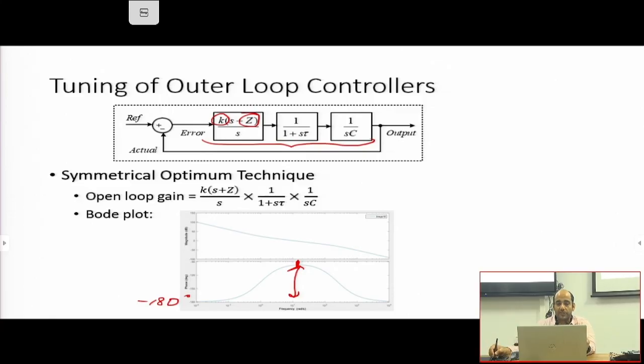So you know what happens now if you see the transfer function here. I hope you can agree with me. If you just change the gain K, it will not affect the phase plot. It was just a gain without any angle. Gain K doesn't carry any angle, right? So it will not add or subtract any angle. It will just give a gain.